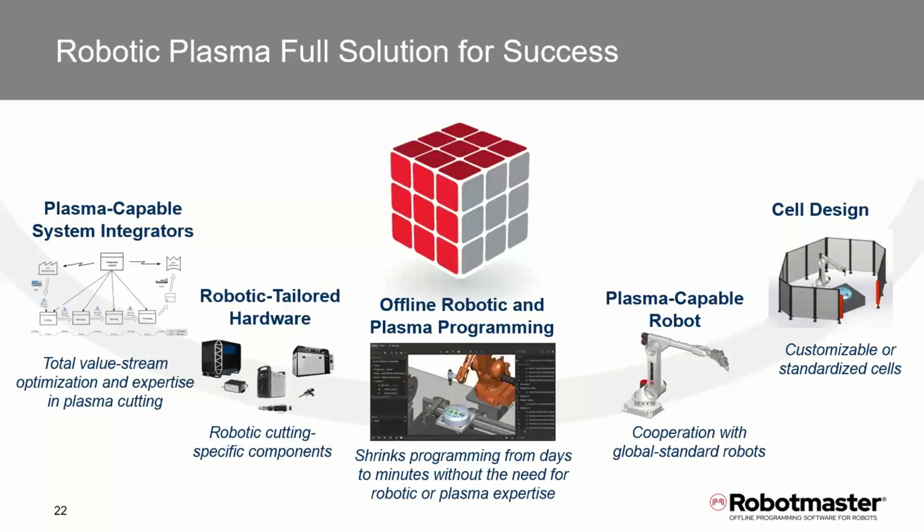Now, if the part is completely different, same approach: you'd import your CAD file and apply your paths using a specific module. We have modules for cutting, spraying, polishing, grinding, and essentially you would select the features of your CAD model. That's what's going to help you generate your path and drive the path, and then from there onto your simulation stage. So it's essentially the same process as you would use for high mix, low volume or high production.